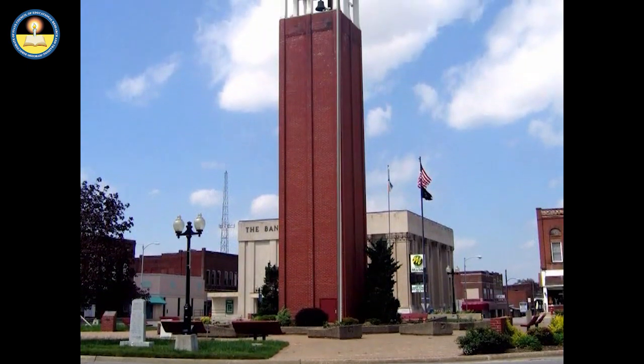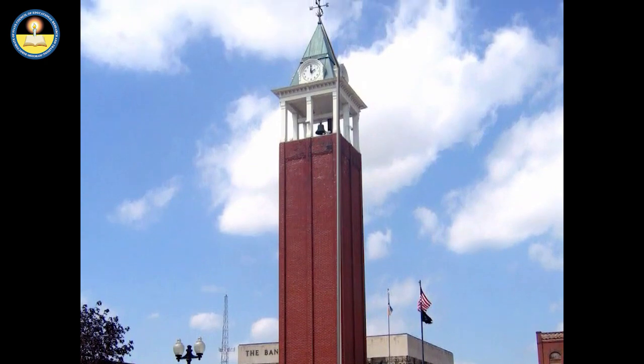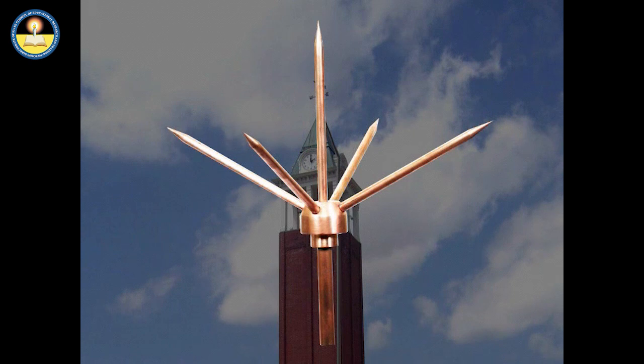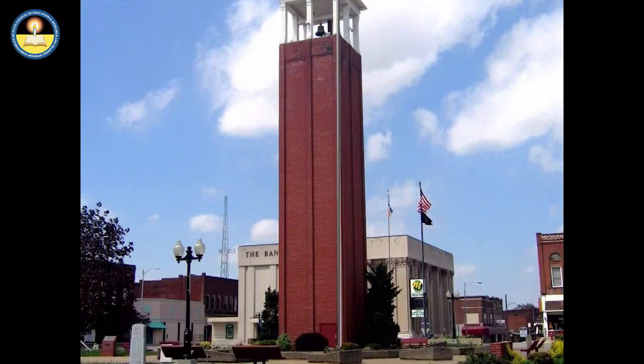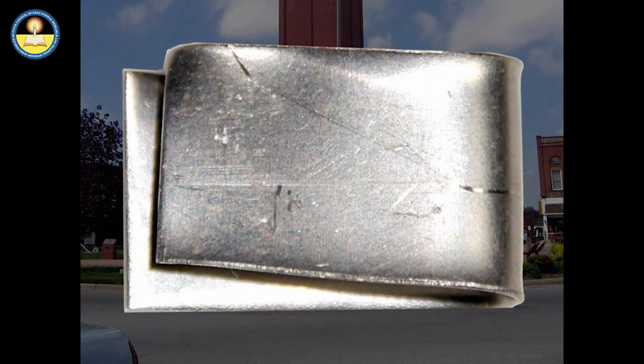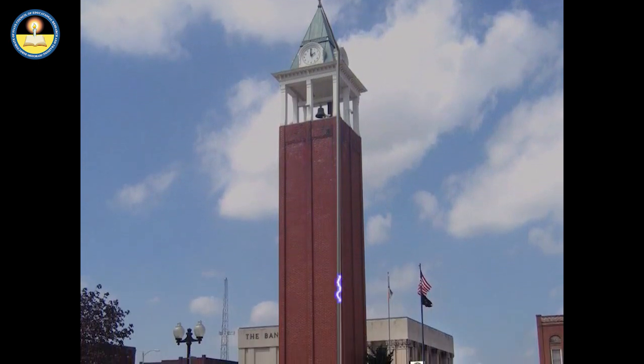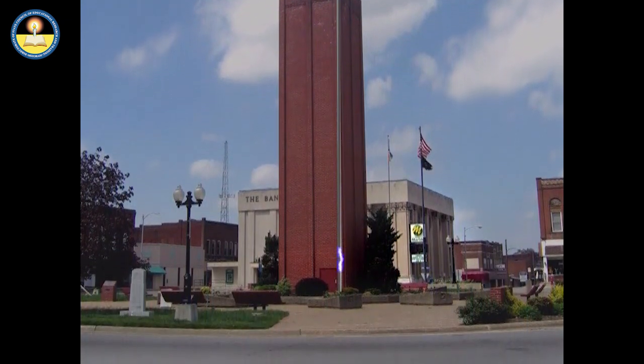As a safety measure, tall buildings are installed with lightning conductors. These are long and thick metal rods whose split upper ends are sharp and pointed, and the lower end is attached to a large metal plate buried deep under the earth. When lightning strikes a building having a lightning conductor, the flow of charges is quickly carried to the lower end of the conductor under the earth and is distributed to the immediate surroundings.